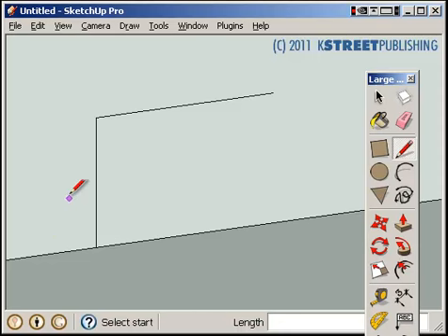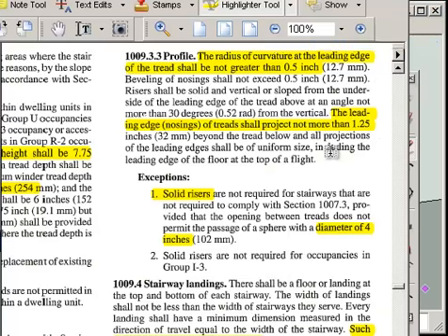Now you might say, well, that's not a real stair. It doesn't have nosing on it. Sometimes risers are put in a slope, but almost all stairs have nosing, so we need to decide how much nosing we want. And even the code tells us what our nosing height. See, our nosing cannot project more than 1.25 inches beyond the tread below.